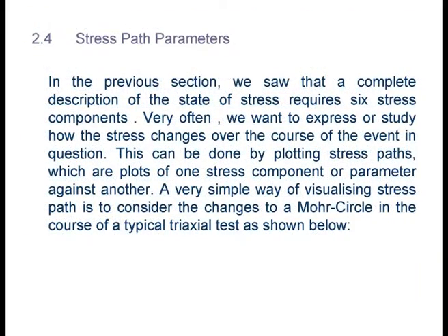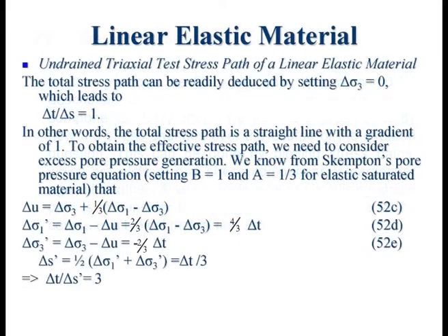So basically, we then went into stress path, and that was the story of S and T and P and Q. Okay, I think I went through the whole set of stress path parameters. Essentially, S and T is very commonly used in practice, where it is also called P and Q. So when you see a graph of P and Q in practice, make sure you check what the definition is. And usually the definition is given together with the axis. Like yesterday, P equals half of this plus this. Then you know it's actually S, because there's a factor of half there.